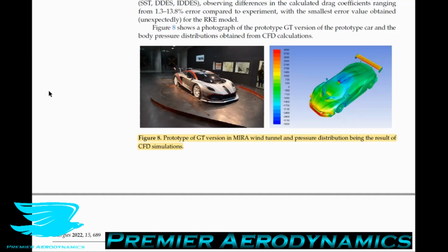That's what LES does. Once we get to a very fine level, we then start to get to what's called the subgrid scale, and that's where we have to use equations to figure out how much energy the very small eddies have. The reason we don't resolve those properly with our mesh is because we would need a very fine mesh to do that, and we would start to verge on DNS kind of meshes, which is impossible to do at the moment based on our computational abilities. So LES is the next full step up from RANS in terms of accuracy. You accurately simulate the large eddies, as the name suggests.